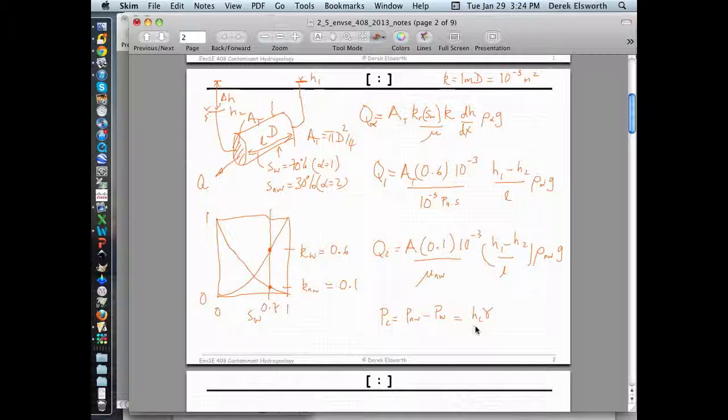So that's fine. So you have a capillary difference that you can use, but of course here you have two potential fluids that you could use the unit weight of, and they're not necessarily the same. And so when we do this simplification for permeability calculations using heads, then intrinsically we've changed a little bit because we're not sure what unit weight we should use in these particular cases because we've messed it around a little bit.